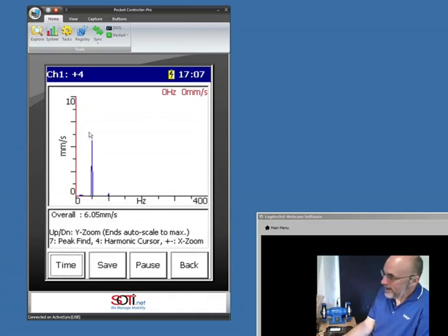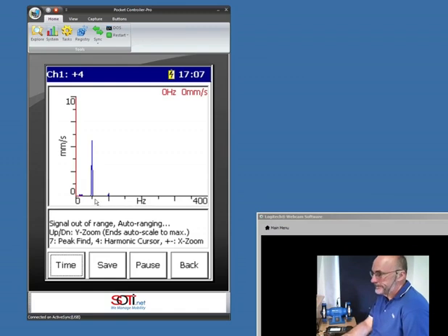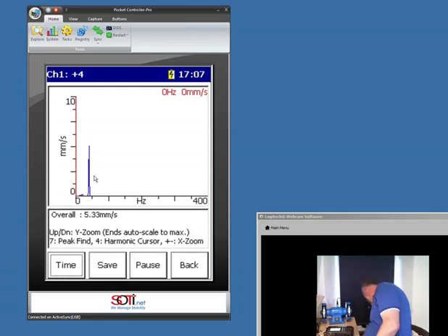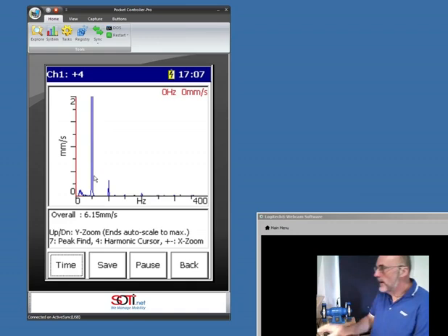Right. So there's my frequency spectrum with vibration velocity on the y-axis, vibration frequency on the x-axis. There is your peak. If I stop the machine and it starts to slow down, that peak is going to start moving left in the spectrum. So you can see it's moving left. But the thing I want to illustrate, to switch it back on, is if I look over here on the right-hand side, there's a little peak there that's showing its head occasionally and it's going back down.